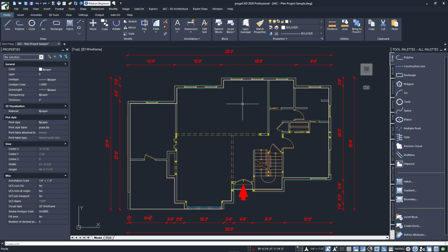You can set a layer to be the current layer. Any newly drawn entities will be assigned to that layer. All layers have various properties, such as color, line type, and line weight. When current, new entities will be drawn using the layer's properties.